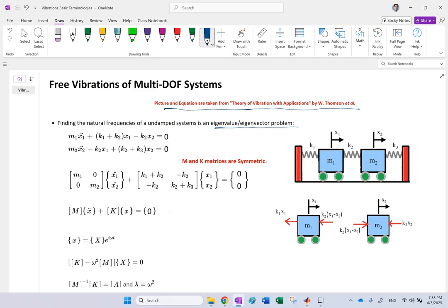How? So here, consider this mass spring system, masses M1 and M2, springs K1, K2, K3. There is no friction below the tires, rolling without slipping. We draw the FBDs of the two objects, and we only include the forces along the X direction. Remember, each one has mg and N, but we really do not need to care about them because all we care about is motion in the X direction. So these mg's and these N's will have no effect in the X direction. So these are your two FBDs.